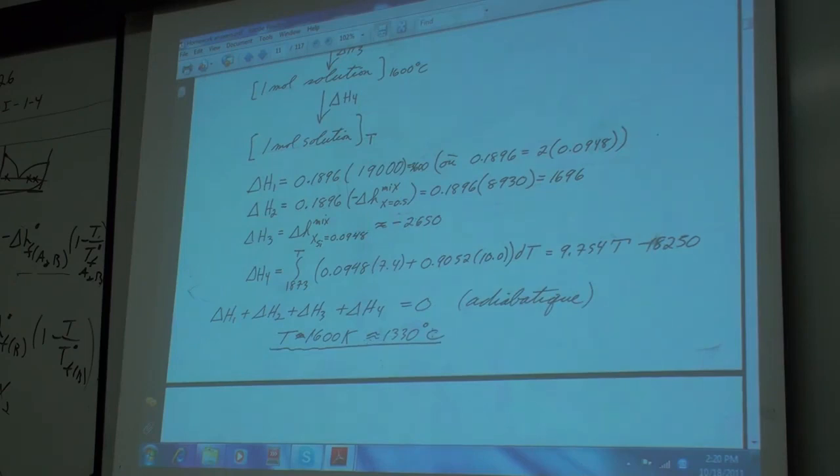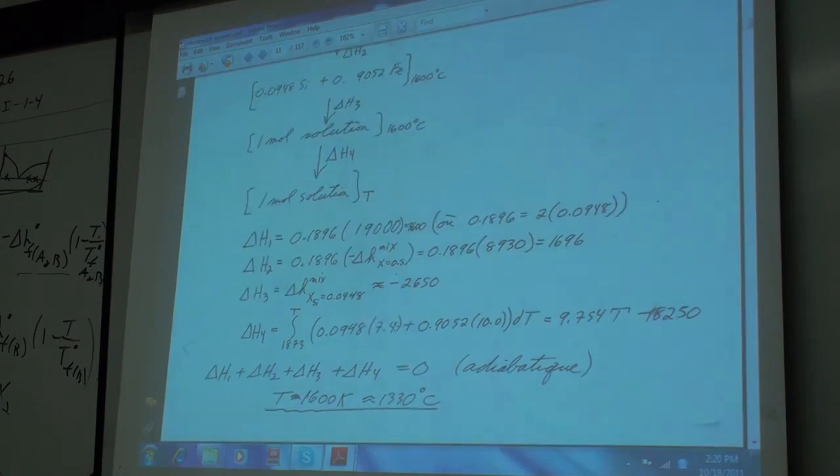So it is lower than 1600, but the reason is I didn't add pure silicon, I added ferrosilicon, so the iron was heating up. But if you do it with just pure silicon, you'll end up actually, I think, with something like 1630. So it more than counteracts. So if you take your bath of steel, you throw in pure silicon, you heat the thing. It's quite amazing.